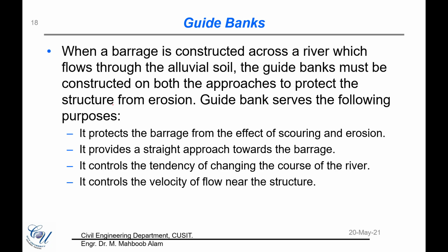So these guide banks ensure that the water is flowing towards the barrages, and that the velocity is maintained in these sections, so that there is no scouring or erosion in areas which are nearer to the diversion headwork.